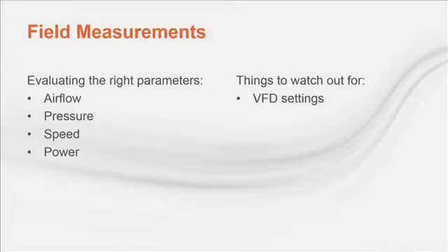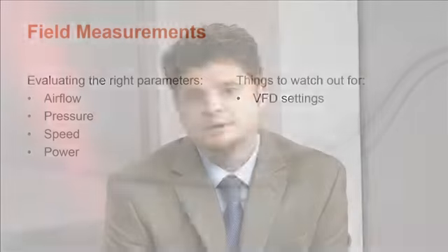If measuring motor power parameters between a VFD and a motor, be sure to use a true RMS meter to account for the modulated waveform. VFD settings in general can be tricky. Energy optimization and variable torque versus constant torque are 2 common settings that can trip up a power measurement. It's best to run the VFD in bypass mode or at line hertz whenever possible to minimize the variables.